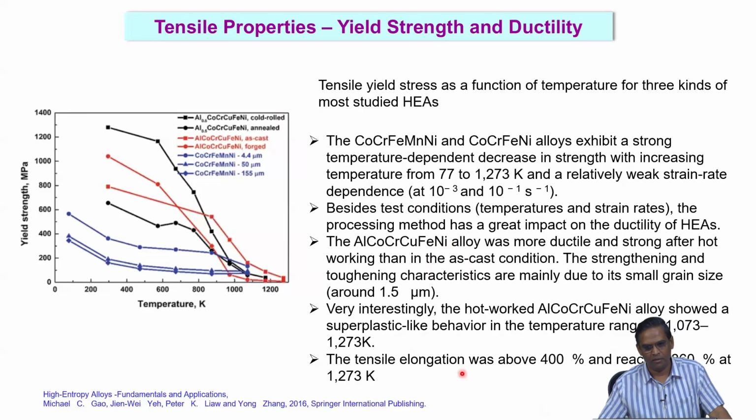For example, if you take titanium alloys, we are now observing negative strain rate sensitivity even in the room temperature test sometimes. So, those are all related to some of the defect structures that develop and so on. There are some specific cases which need to be really looked at. We cannot generalize. Okay.